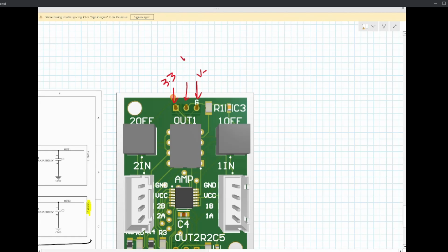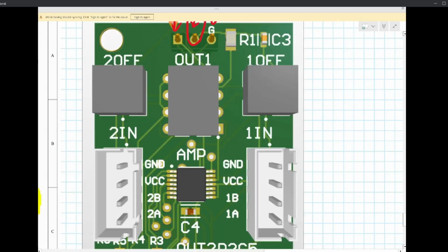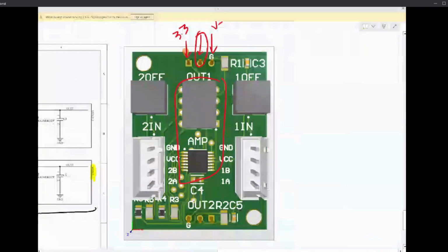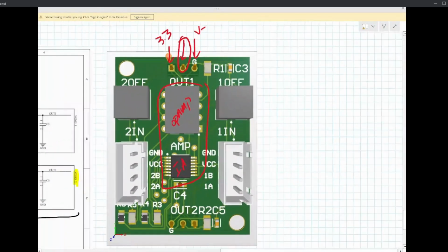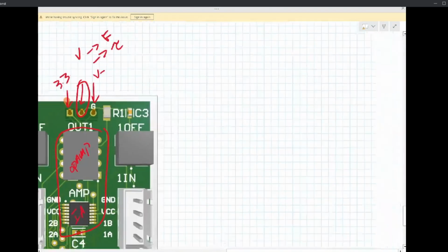This is where you're doing your voltage to force, your voltage to torque transformation. You're doing it on the values that are coming out of this pin. Other things on here, we have one op amp and an instrumental amplifier. This is the op amp. This is the instrumental amplifier. You have an offset, which I'll explain what that does in a little bit, and a bunch of resistors and capacitors.